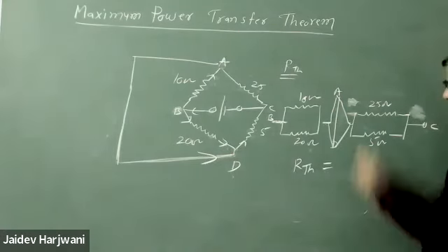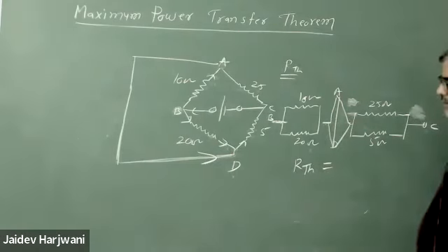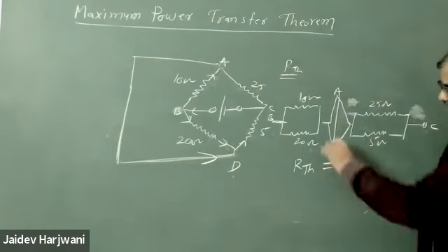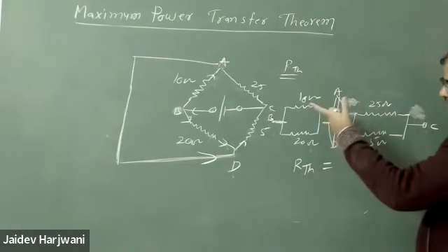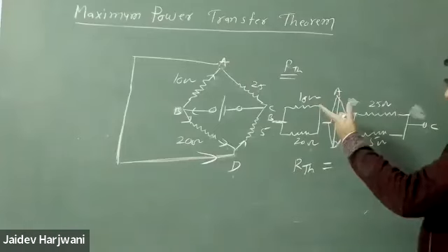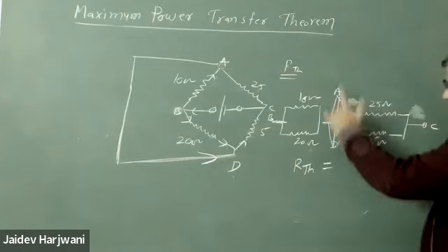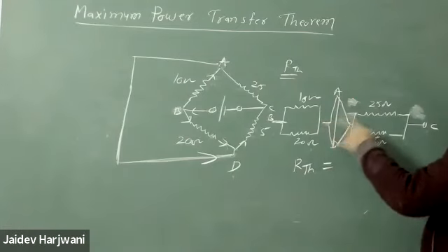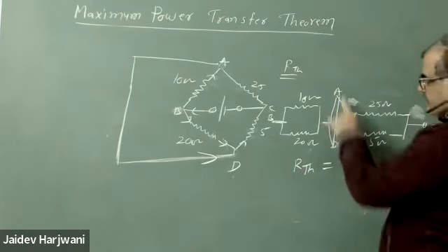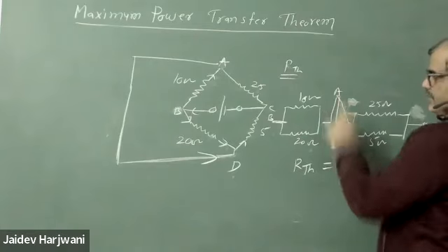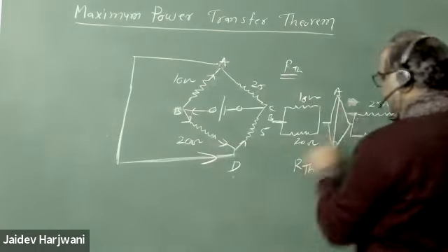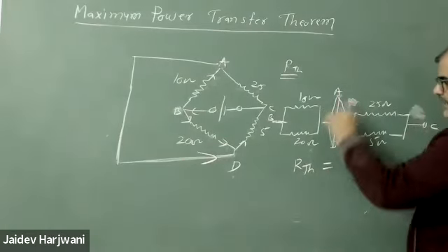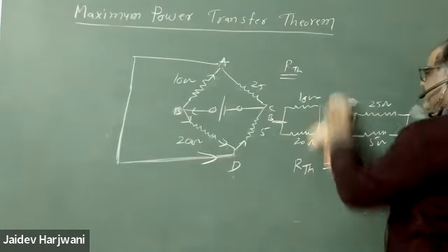What difference has this made? There is no resistance. Okay, there is no resistance, this is the same point. Whatever current will go here, suppose you say current divides, total current will go here. So there's no potential difference because they're shorted now. A to B line, A to D. They're connected, so that is one point only.